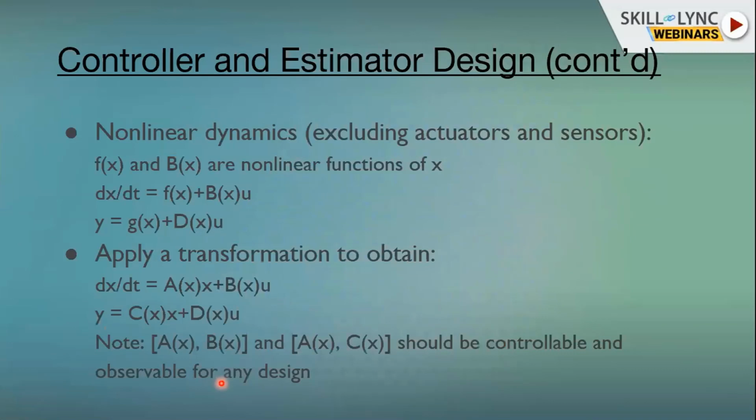So the underlying algorithm for the controller and estimator design, the tools are provided. Once you build a model in Matlab Simulink, you can design a control law and an estimator with that information. All you have to do is extract a bunch of linear models at different operating points and use those linear models to design controllers or gain matrices at those operating points. And Matlab has solvers for those.